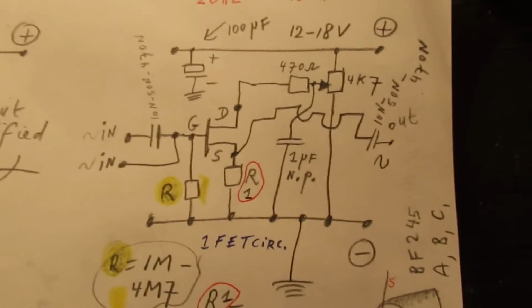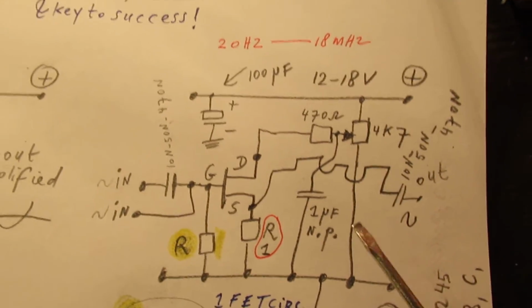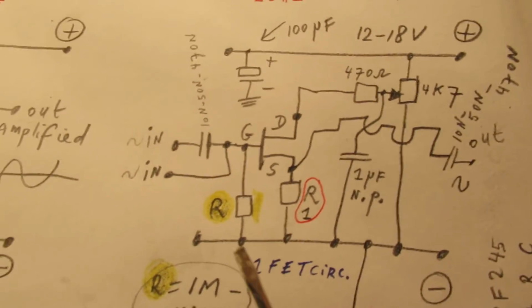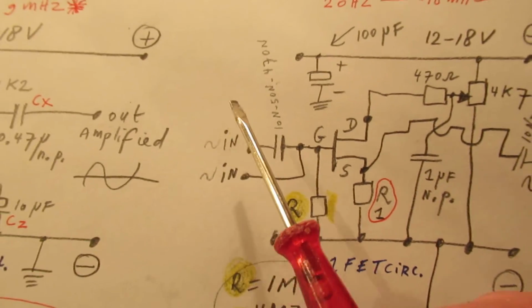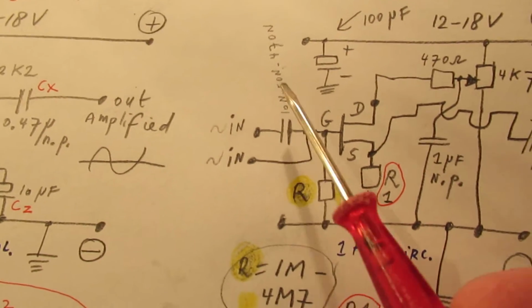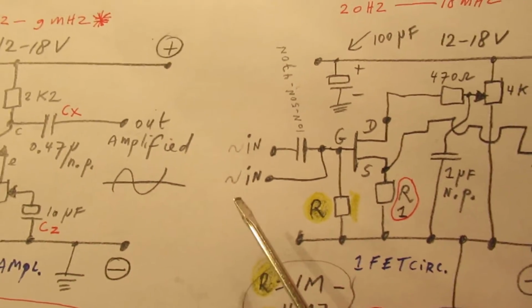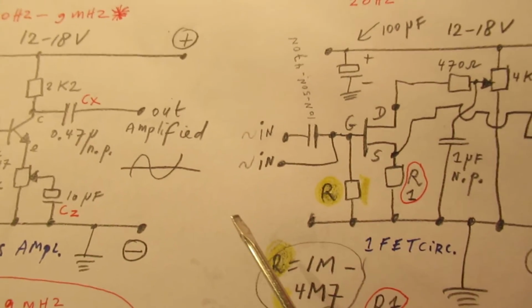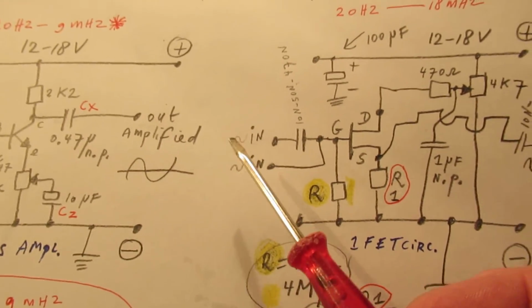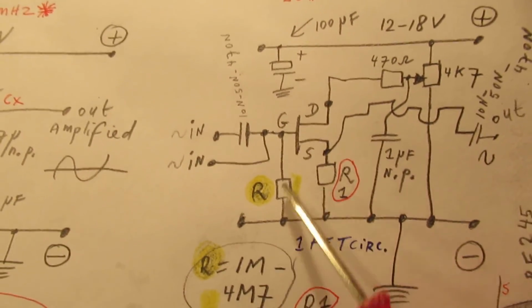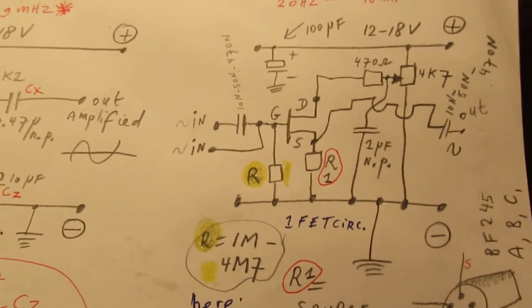And you can use this circuit, for instance, not only for high frequency circuits, but also for audio filters. Then the audio filter unit is here at the input. Say it's tuned to 2 kHz or 3 kHz, and it doesn't lose its good properties because the input impedance here is extremely high.